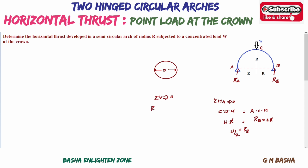The sum of the vertical reactions on the arch will be equal to W. RA and RB act upwards and W acts downwards. We already know RB, so RA will be equal to W minus W by 2, which is W by 2. That is the RA value. Or we also know one condition: on a simply supported beam, if a point load is acting exactly at the center, the load will be distributed equally on both ends. Like that also you can consider directly. So our first step is to find the vertical reactions at A and B.